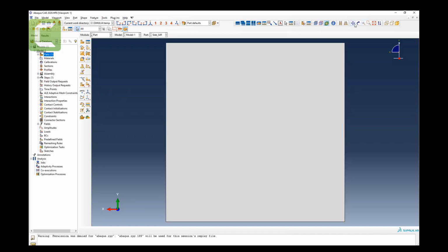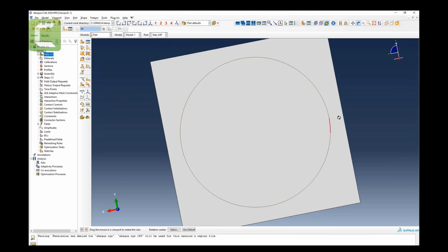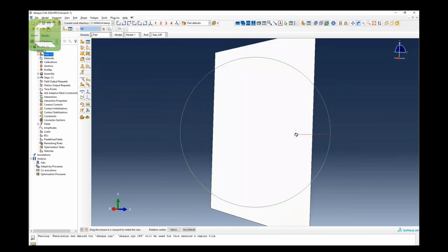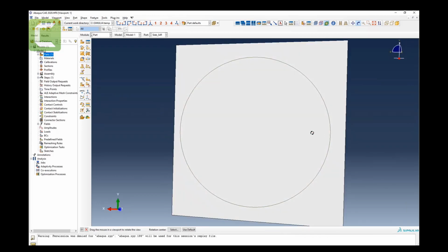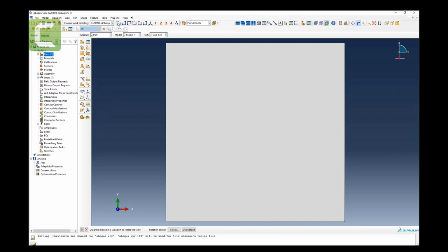Right, you can rotate as well. If you have this button, rotate view, Control Alt MB1. If you do this, you can rotate it in any direction. So you can see that. Very simple. If you want to keep it in any of these orientations, you can come back here in the view and do it that way as well. Any questions? Any comments? So far so good.